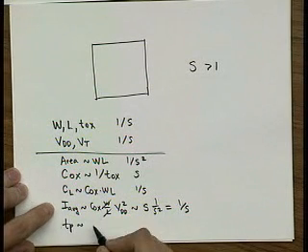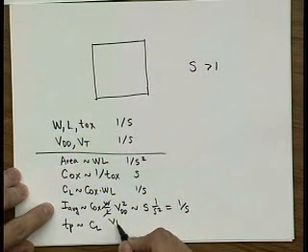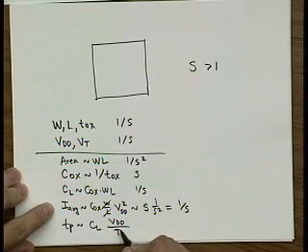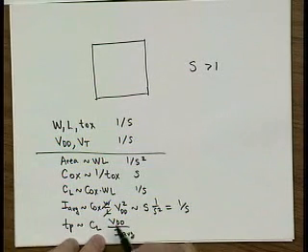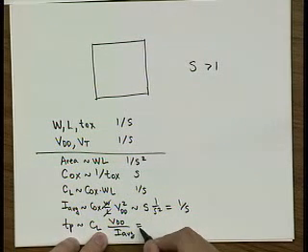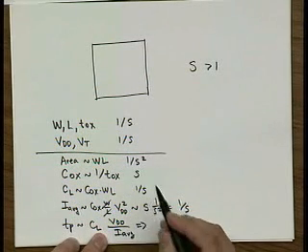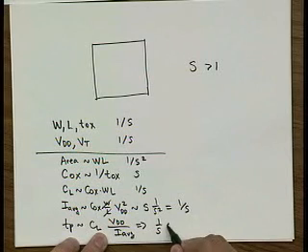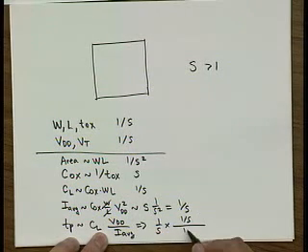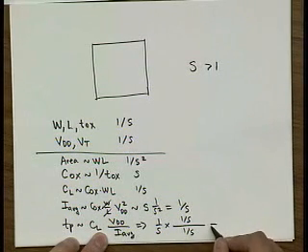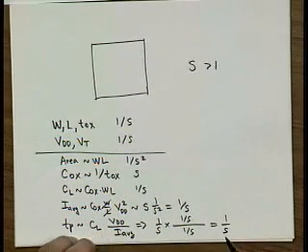Propagation delay is proportional to the load capacitance, voltage swing, and average current. This is basically your equivalent resistance. So now CL goes as 1 over S, the voltage goes as 1 over S, and your average current also goes as 1 over S. So propagation delay ends up improving with this factor 1 over S.